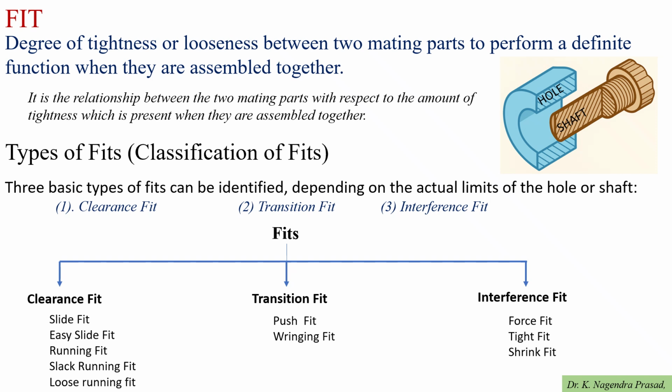These fits are subclassified. The clearance fit is subclassified as slide fit, easy slide fit, running fit, slack running fit, and loose running fit. Similarly, transition fit is subclassified into push fit and wringing fit. Similarly, interference fit is subclassified into force fit, tight fit and shrink fit.